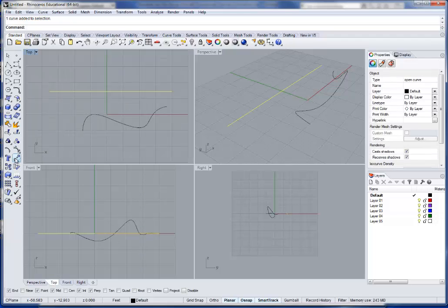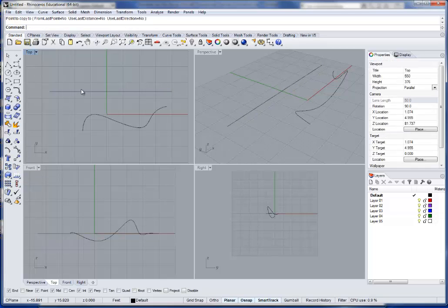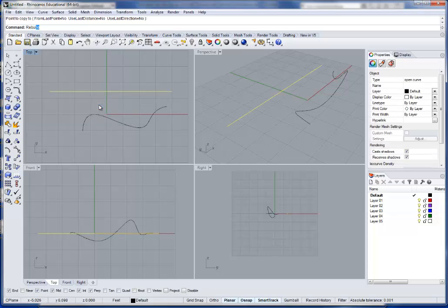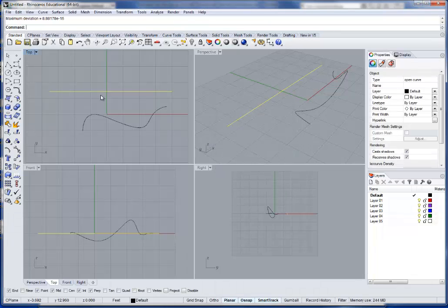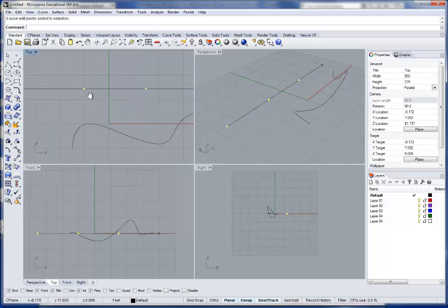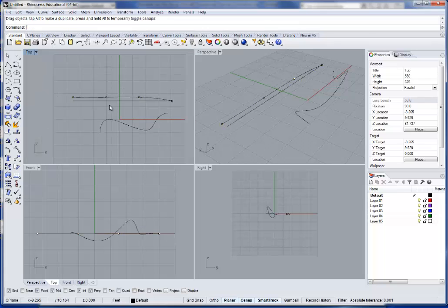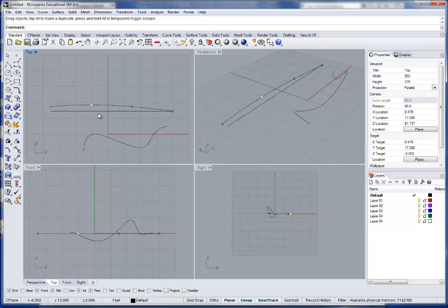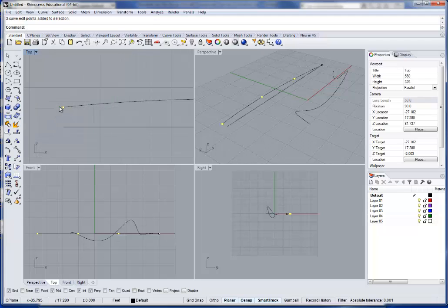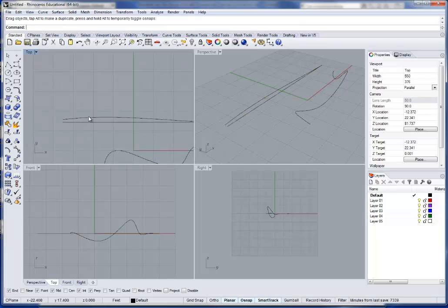And so now I'm going to go ahead and create a blade of grass quickly here. I just replicated that curve, and I'm going to rebuild it as a 3-degree curve with 3 control points. Hit OK. Alright, and so I'm going to take these and just pull them off. And I'm going to pull this out. So it's a pretty wide blade of grass there, especially since it's 75 feet long. But I'm just going to pull this back, hit escape.